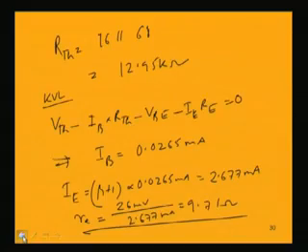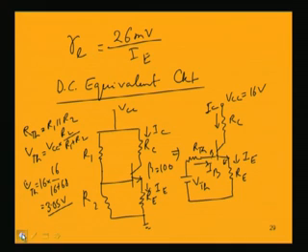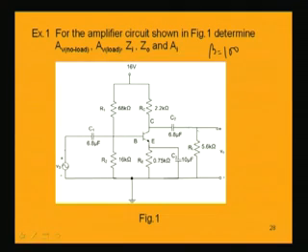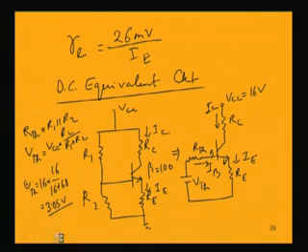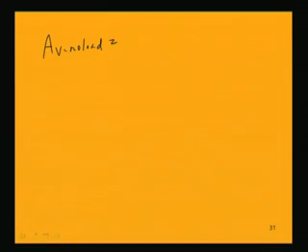Of course, here if we consider the no load voltage gain, AV no load, we will have to look into the circuit to find it, and the no load voltage gain and loaded voltage gain will be different, because the no load case will have no load here. So the circuit will have only RC, and R naught is not mentioned. So we will find the no load gain as V naught by Vi, which equals minus I naught into RC by Vi.